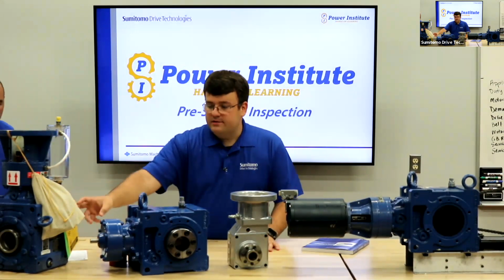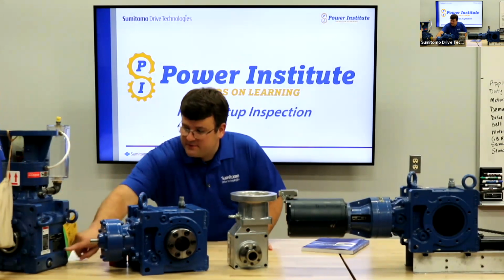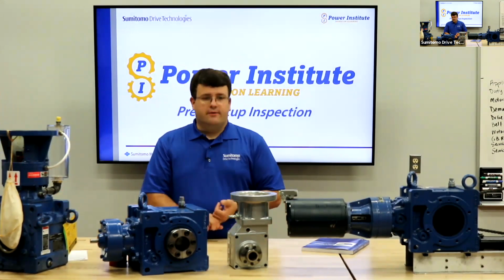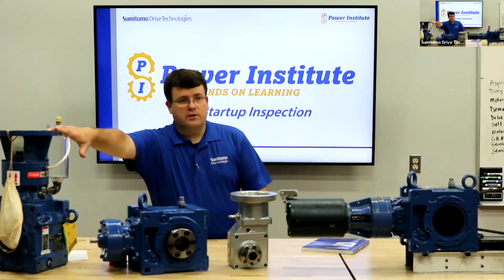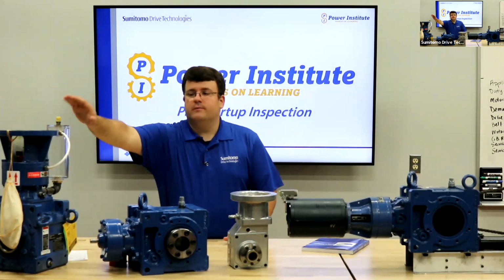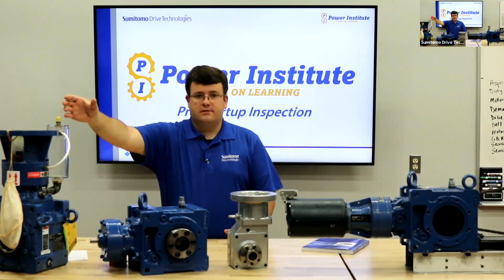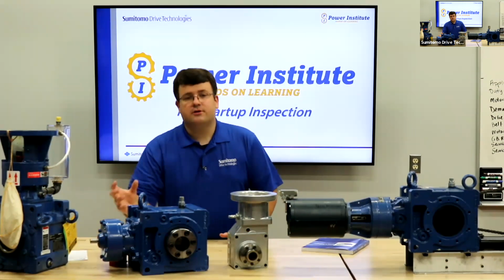So here's our Y2. We'll go over here to the name tag and make sure it's the correct selection. It's the right frame size. It's the right ratio. In this case, we didn't order it with a motor. So with our existing motor, make sure it's the right frame size at that motor adapter here, so our motor will bolt right to it. You're going to check all that. Make sure it's what you ordered.